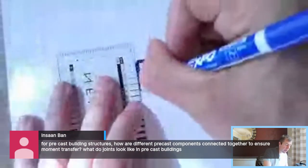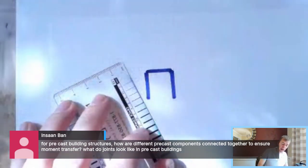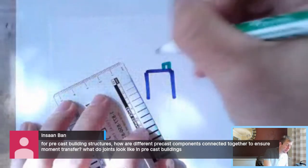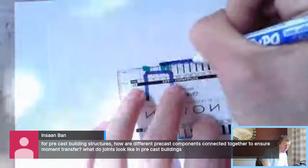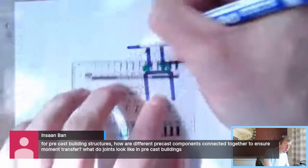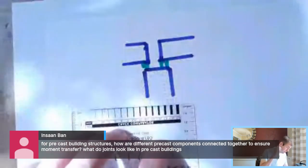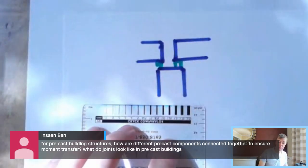It's common. I may have a column down here. I may have a bearing pad, some kind of temporary bearing pad that's put in place here and here. I may put a beam. A beam may go here. A beam. And a beam here. This is commonly used in California, this type system. And I'm assuming you want it to be moment transfer. So we're going to assume seismic detailing here.